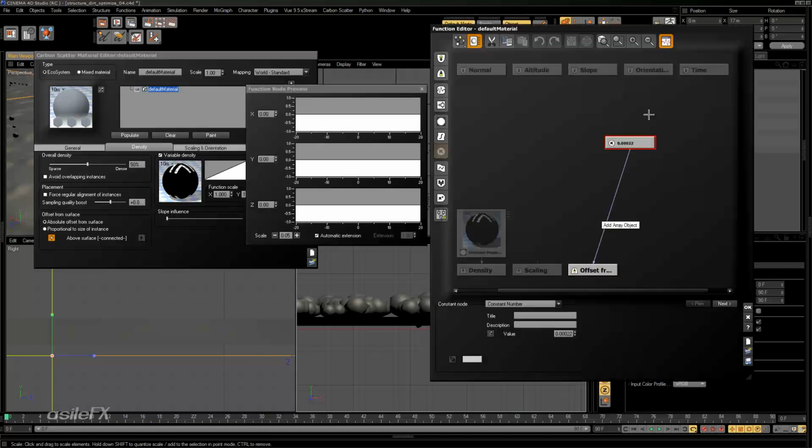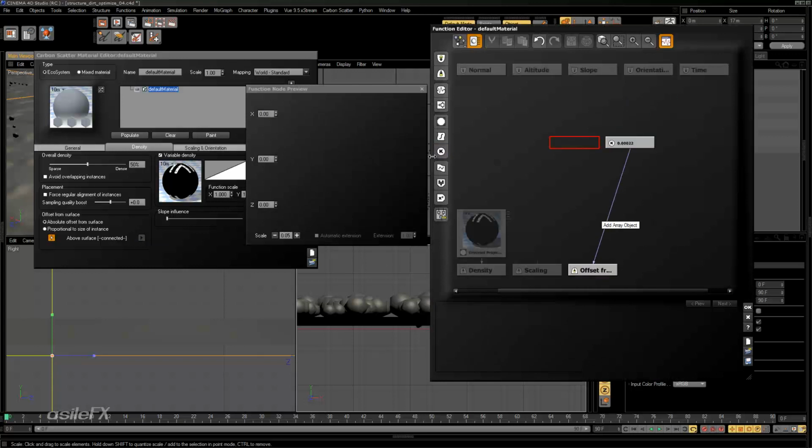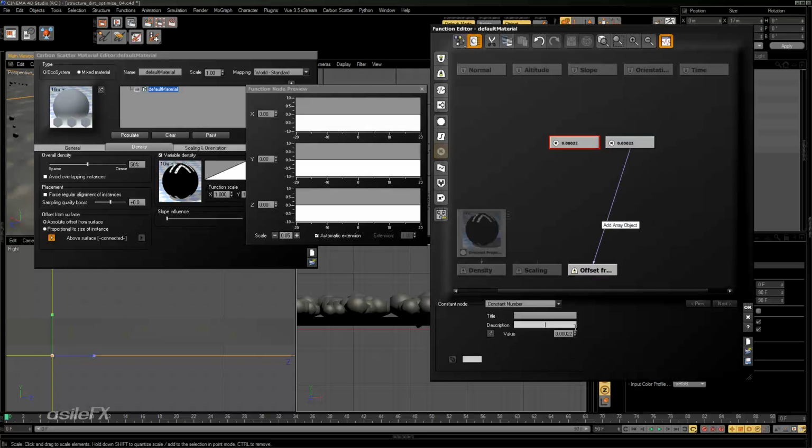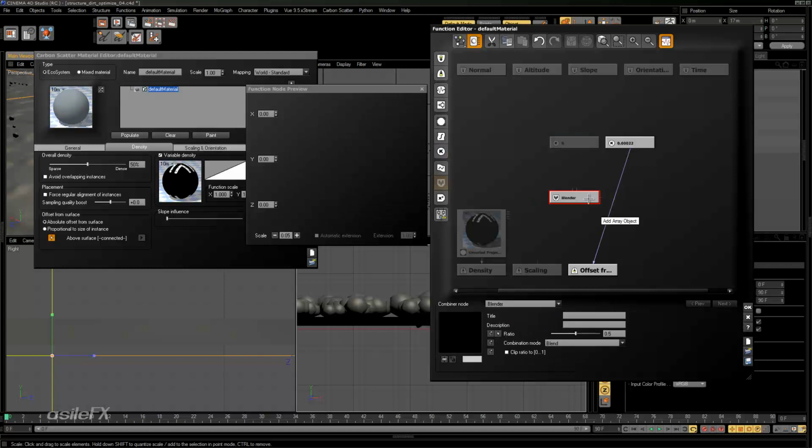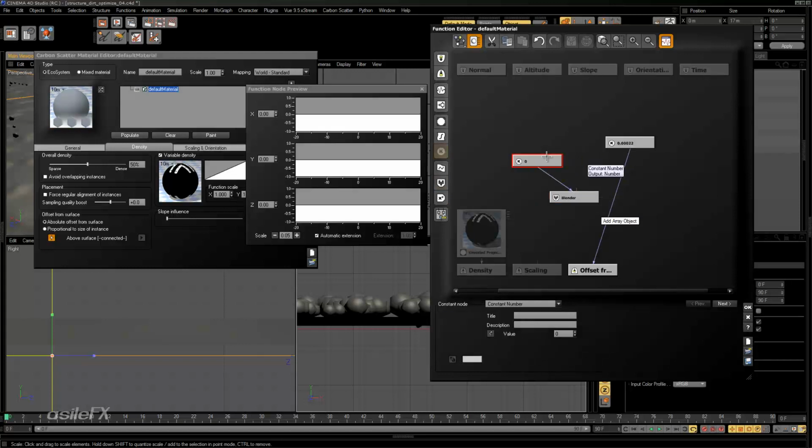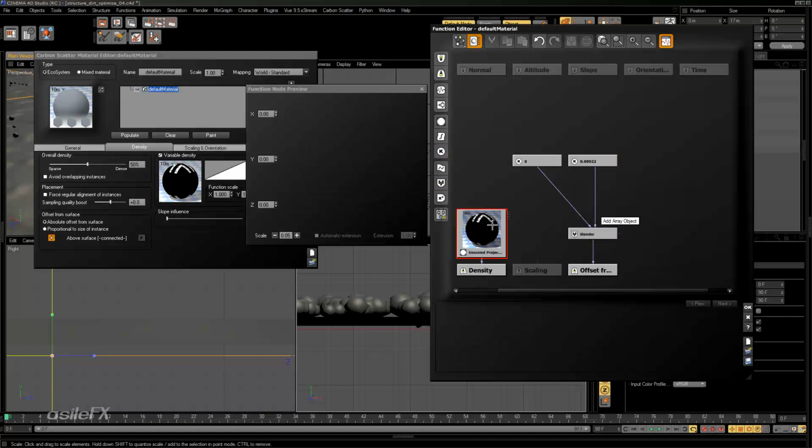And what we're going to do is set up another constant node of 0, add in our blender. So a combiner node set to blender. Input 0 is going to be connected to that constant node of 0, constant number 0. Input 1 is going to be that constant we extracted. We can replace the link for the offset to the blender and now load in the image.